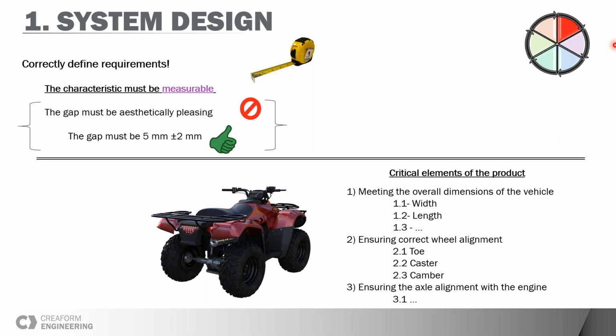We're going to develop a product for a company, and then once the product is being assembled, maybe 2 years later, they figure out they have issues on the production line. Some components take longer to assemble because the door doesn't close flush, so you have to find out what the problem is. You have to inspect, maybe with laser trackers, or the IndyPro, whatever technology you use. And you'll have someone like Cedric making sure you're taking the proper measurements, looking at the engineering drawings, making sure we understand the functional requirements.